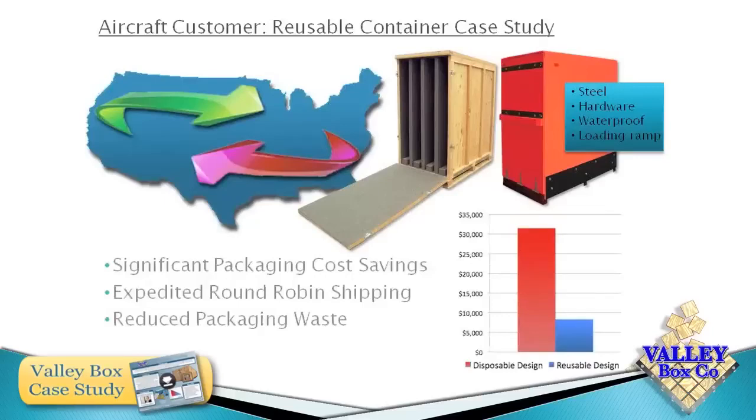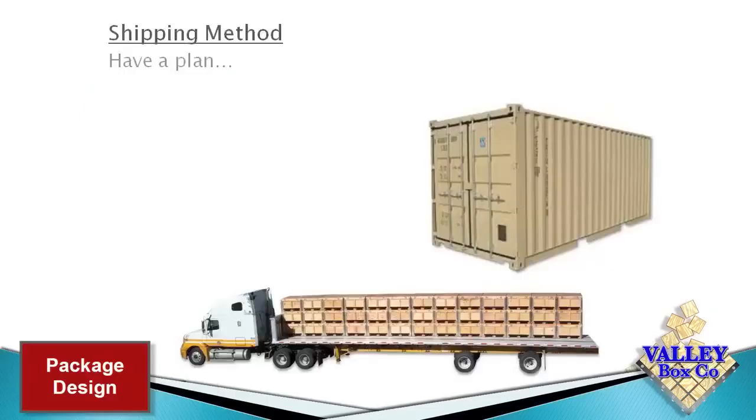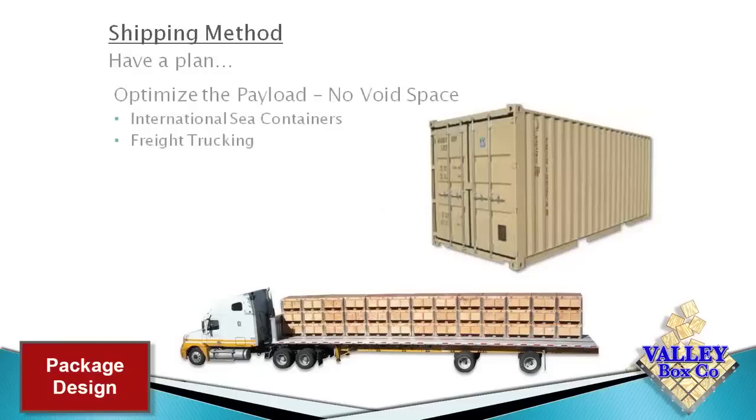So why does it matter to have a plan prior to shipment? Well, if you're utilizing international sea containers or freight trucking, the cost can be dramatically reduced by designing packaging to optimize the payload. By implementing a packaging plan in advance, you can load a higher value of goods while the freight charges remain constant. When voids of space occur within the load, blocking and bracing is necessary to avoid load shifting that can potentially destroy the contents.